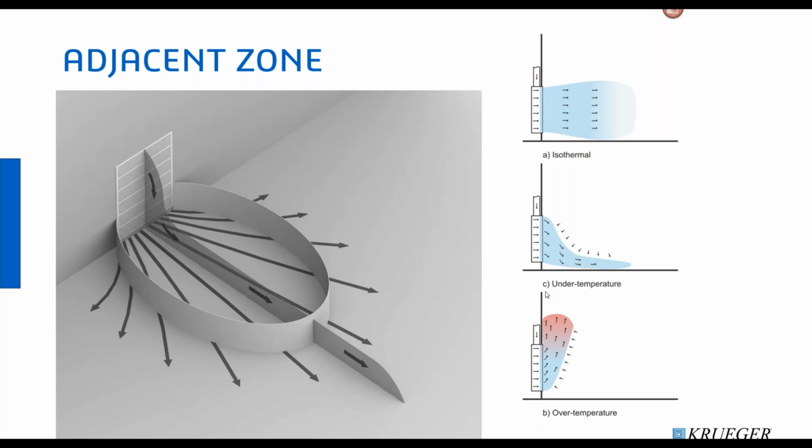However, in heating, displacement does not work quite as well because of the buoyancy forces that take effect on that warm air. Since we're discharging the warm air at a lower velocity, it tends to head towards the ceiling like a hot air balloon rather quickly. So heating out of a displacement device isn't exactly ideal. However,